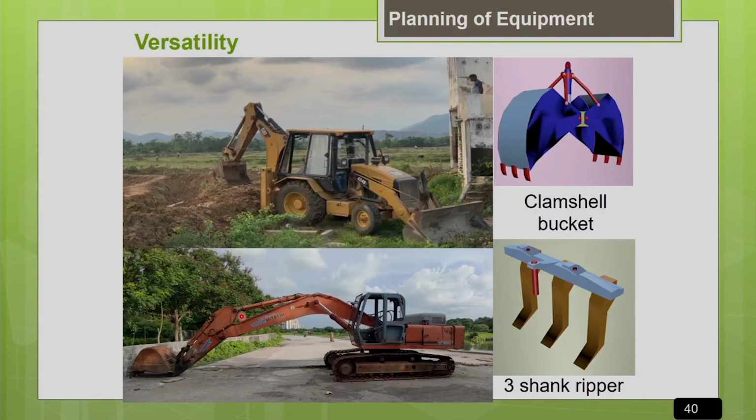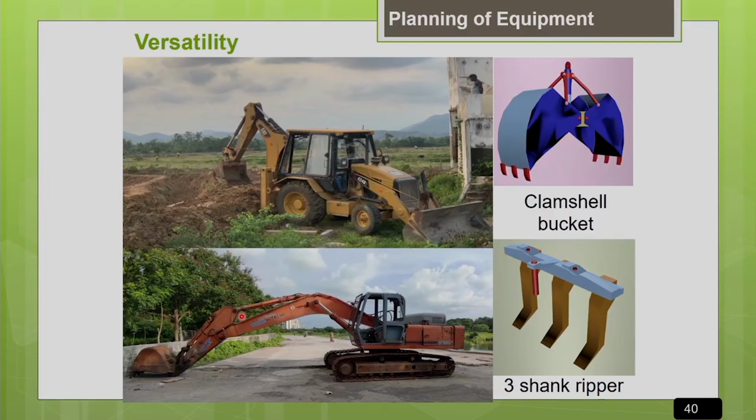So far we have discussed different factors which affect the equipment selection process. I will just summarize: from this discussion we know that the important factors which affect the equipment selection are the productivity and the cost associated with the machine, and you have to look into the contract specifications to know the actual job productivity requirement. Accordingly, you have to select the machine with the matching productivity, and you also have to check that the cost associated with the machine will fit into the project cost. Other than these things, your job site conditions and the job site location also influence the selection of the machine significantly.